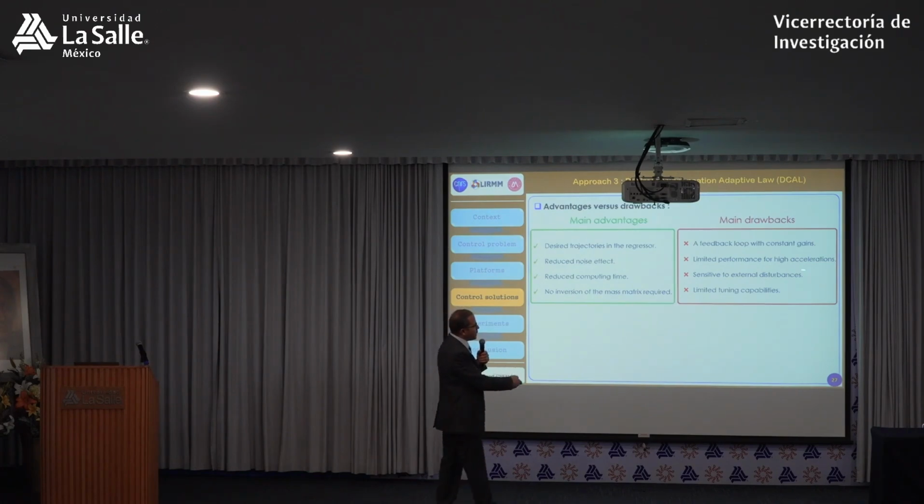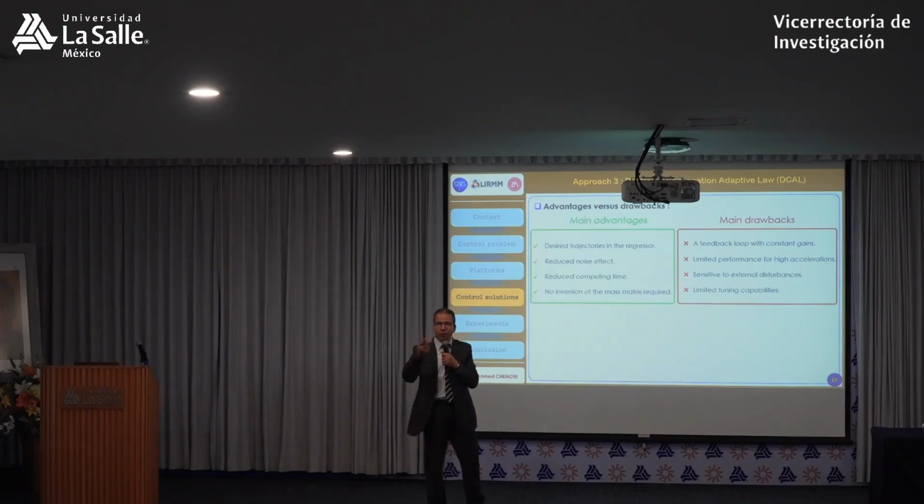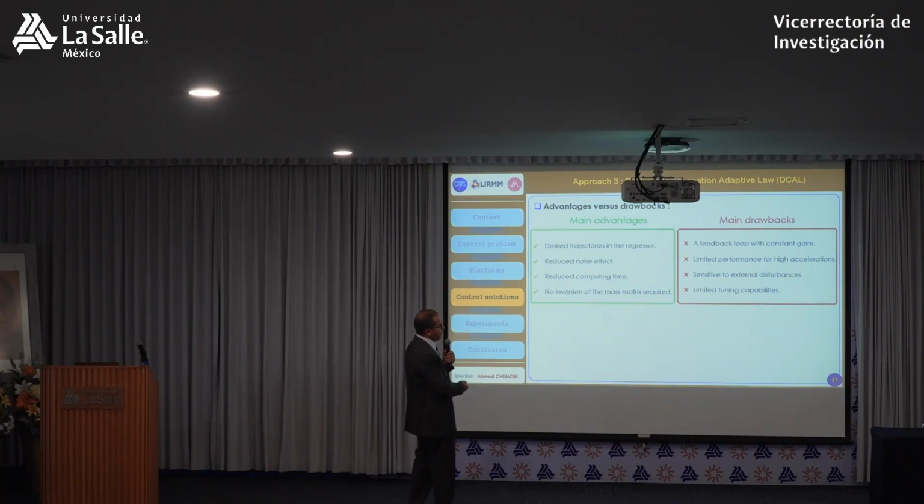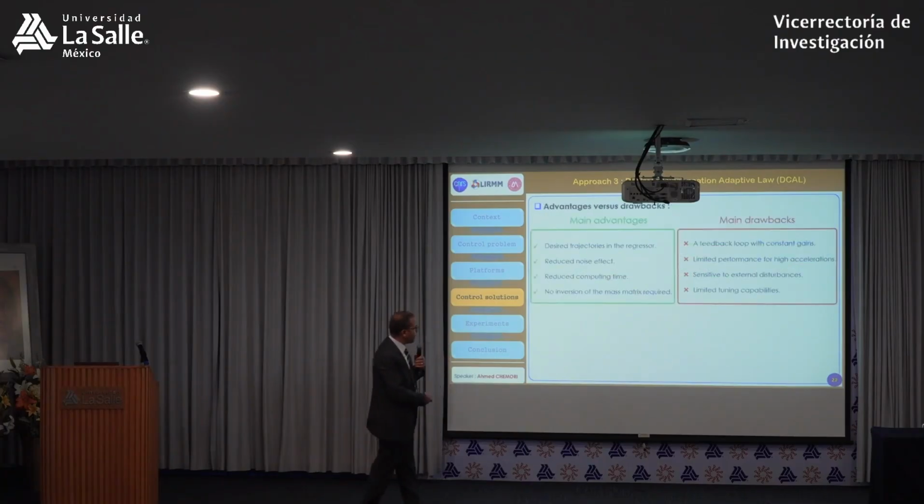in this case. Sensitive to external disturbances also, if you have something that modifies the environment or the robot itself, or the interaction or the objects. So this may generate this sensitivity to external disturbances, and limited tuning capabilities because the gains here are fixed.